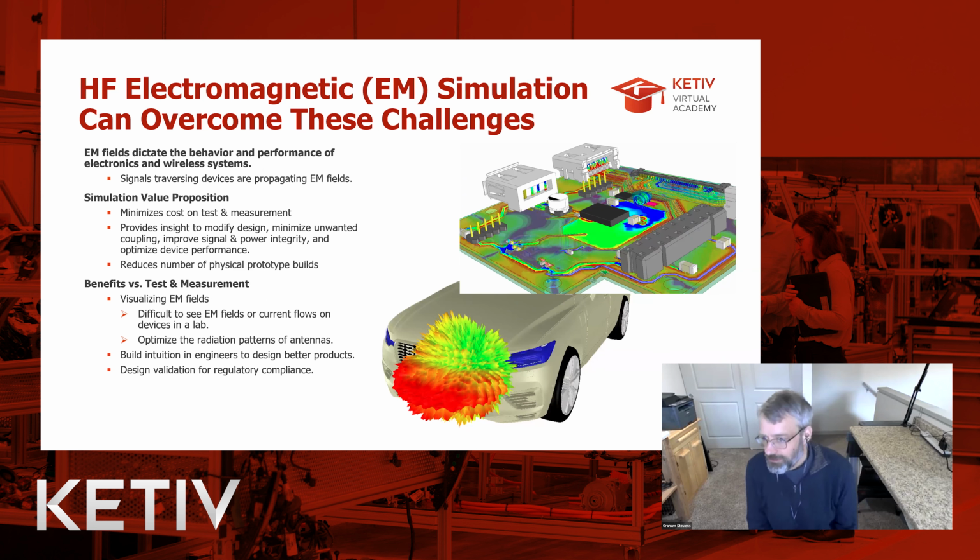So we're using simulation, in particular Ansys's HFSS software, to overcome these design challenges. With HFSS software, we can actually visualize, as you can see here in this slide, the fields, and what is going on over time. We can visualize the antenna's radiation pattern, its gain, what it actually looks like, even though the EM fields, of course, are invisible to our eyes. This allows us to look at the antenna's performance before we've ever built the antenna in the first place, which allows us to modify the design, improve coupling, improve signal and power integrity, and hopefully, if the simulation is very accurate compared to what the actual prototype does, you can eliminate design build cycles.